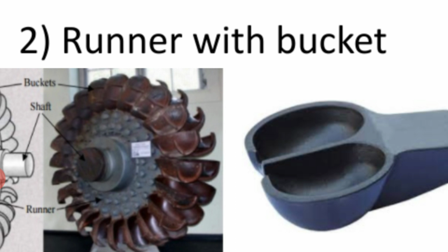The surface at these portions is raised, and water striking at these portions will not be able to turn through 160 to 170 degrees, which is the desired angle required in a Pelton wheel, but instead it will be deflected back, thereby disturbing the incoming bucket.